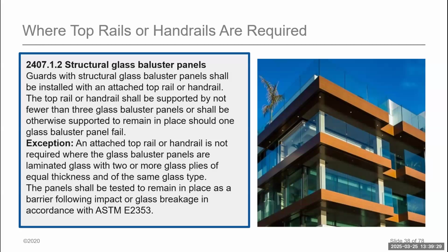The other thing we also have to be cognizant of is the allowable deflection design standard. We would like to see 1/2 to 3/4, no more than an inch, as a standard. The thing is that 9/16 inch glass will deflect more than the glass thickness itself under its allowable deflection.